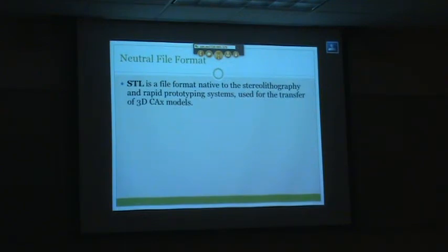And then they would slice through the triangles with planes, and those planar cuts would then be sent off to a stereolithography machine, and they would cure the material, and it would sink down into the vat, and they would cure another layer, and it would sink down. But it was all off of a triangular representation of the data. So if you say output an STL, can you take that STL and go to another CAD system and say, bring it in? You can. What are you going to get? Triangles. But it is a way to move the model to another system.